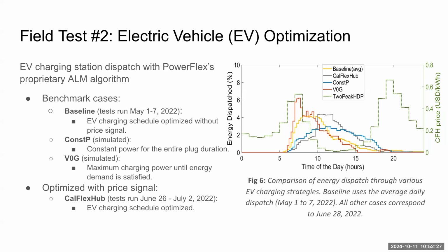Yeah, so now there are lots of lines here, and that's because with EVs, you have a bit more complicated scenario of which way you go about charging these cars. And so we did a couple of different options here. The most intuitive one is what we call V0G. That's not really a technical term. So V1G means you only charge. V2G means you can charge and discharge, so two-directional. V0G, there's no such thing as zero-directional, but it's the dumber version, the dumbest version that's out there. So in that sense, the zero makes sense because it's step zero.